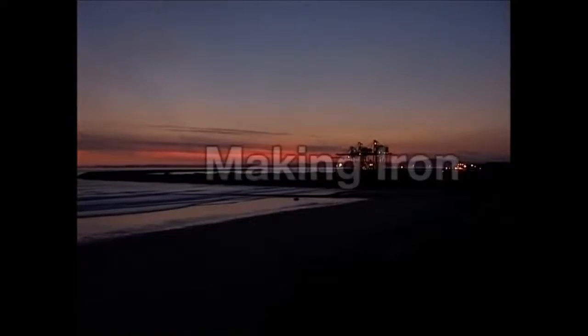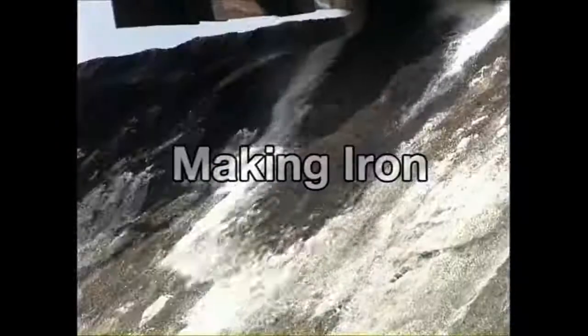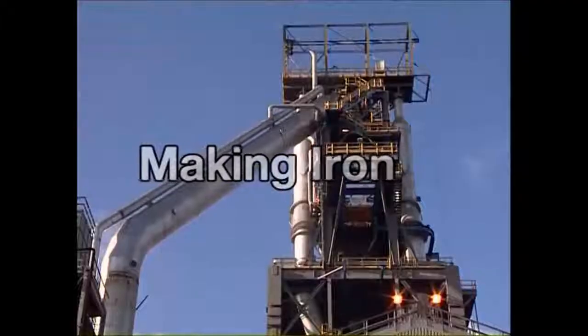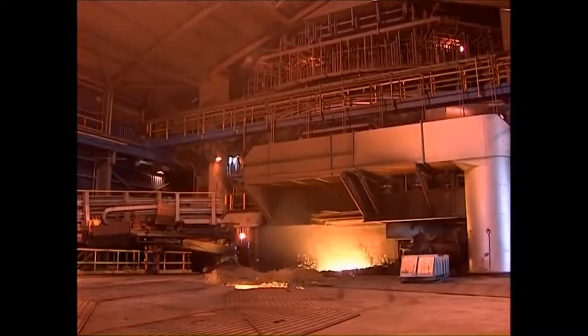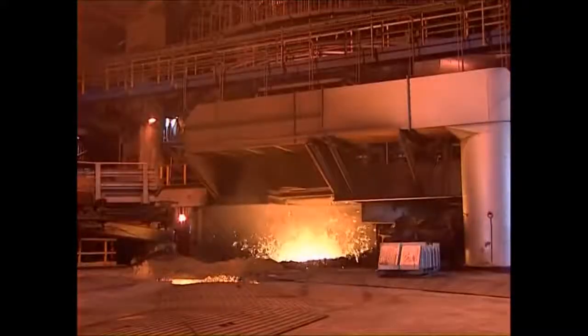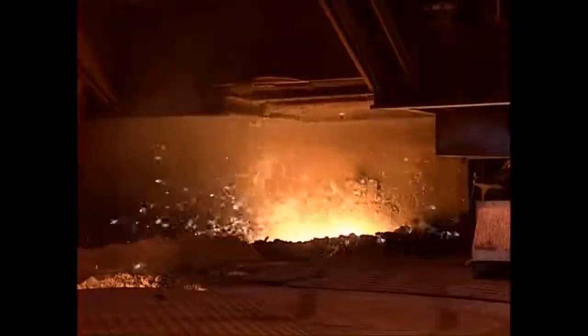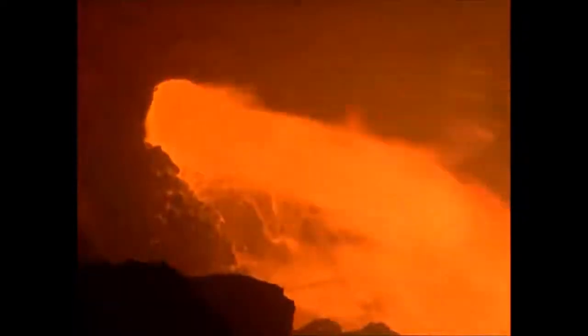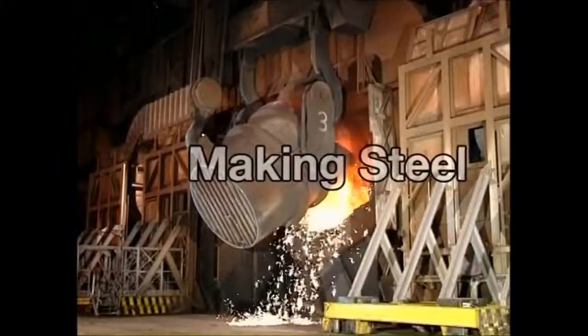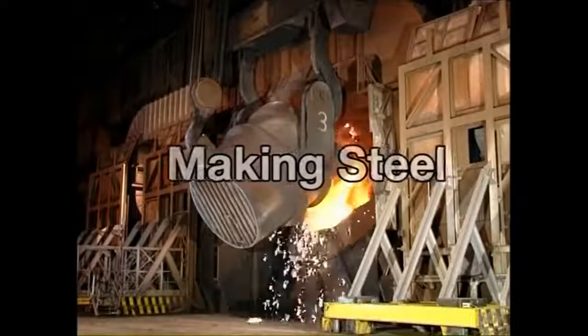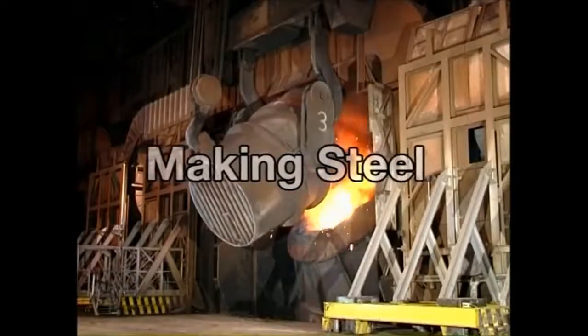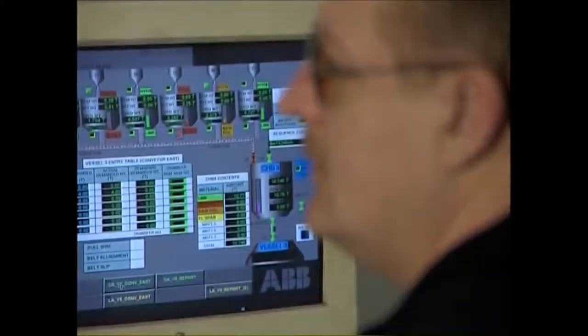Well, the quick answer is you take iron ore, coke and limestone and put it in the top of a blast furnace. Blast air at it until it's hot, very hot, white hot in fact. And out of the bottom you get molten iron, the material from which steel is made. Making molten iron into steel involves removing some impurities, such as carbon and silicon. In other words, it has to be refined, and this is done by blowing oxygen onto it.